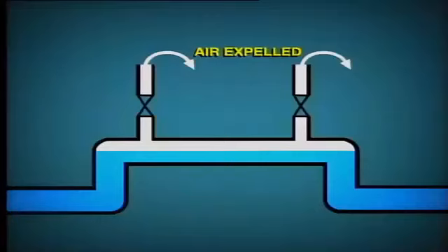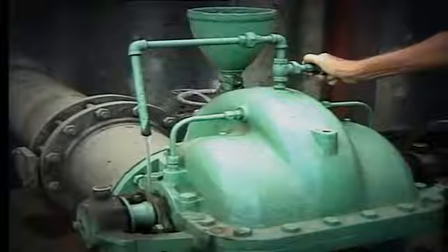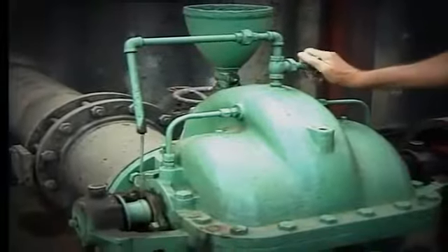We have mentioned the importance of adequate venting of feed water heaters, but venting is also necessary when filling the piping system with water in preparation for operation. All of the condensate and feed water piping is fitted with high point vents discharging to atmosphere. When the system is being filled, it's important that the vents remain open to allow air to be discharged. When water can be seen exhausting from the vents, they may be closed. Equipment such as pumps and heat exchangers are treated similarly.